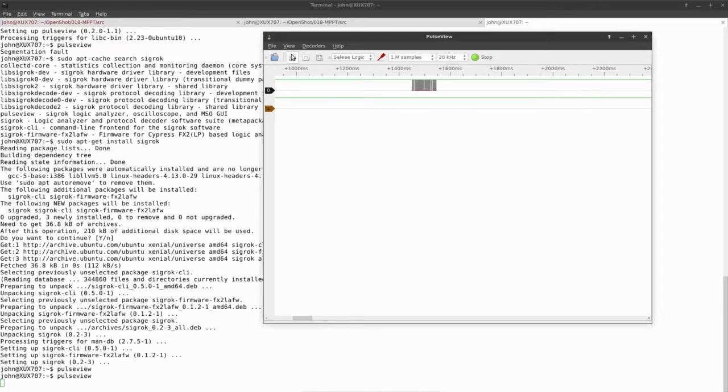Now if we didn't have the actual documentation from Victron Energy, we could look at this, determine the smallest little pulse, and work out what frequency we're running, get an idea of what the start and stop bits are and all the rest of the protocol. But we don't need to do that because we have the documentation.